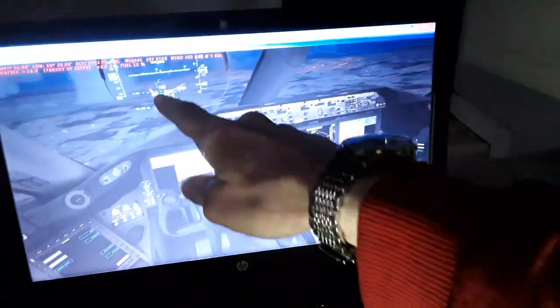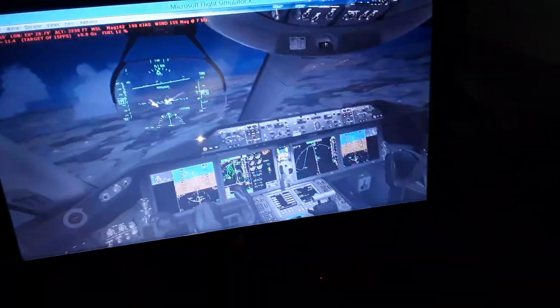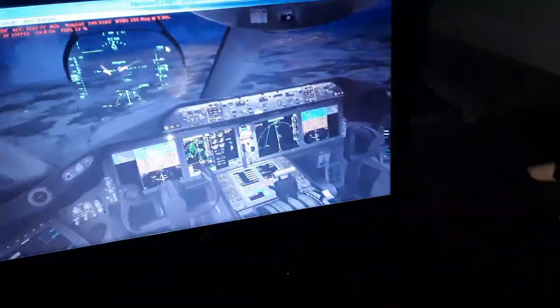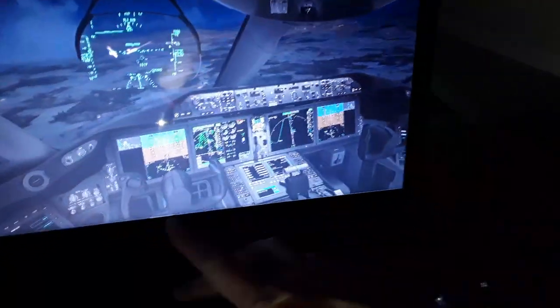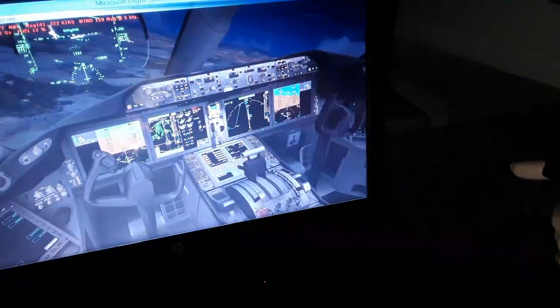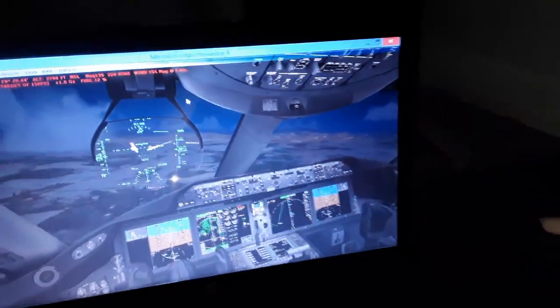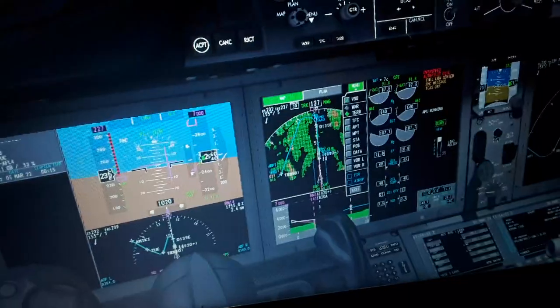We are a little bit off runway alignment. So we have some side wind, some wind gusts. We need to align with the side wind and the wind gusts. Also add some thrust, some flaps, more flaps over here. So we are now aligned, left rudder now for the runway alignment. As you can see, we have also the ILS localizer, all the information we need to follow in the displays.